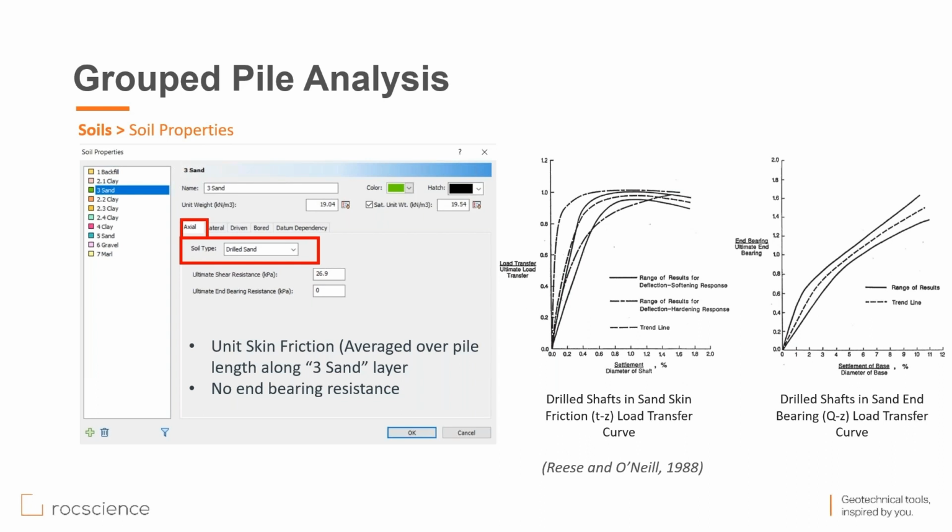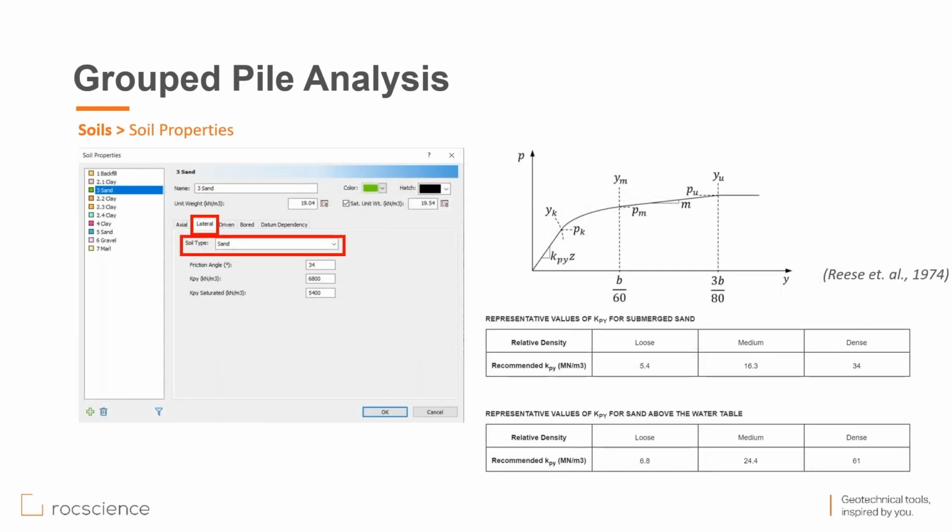However, this time, to calculate the load settlement behavior and the reaction curves of these piles, Reese and O'Neill's developed charts for sand come into action and help you. So the major remark is, be sure to go along with the documentation the software has presented while selecting your soil models.